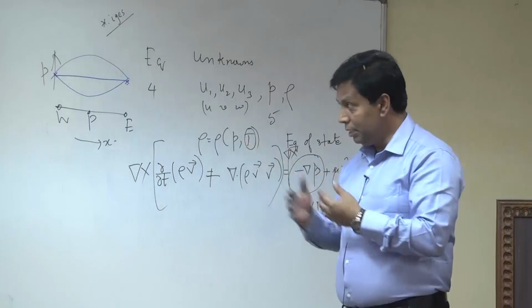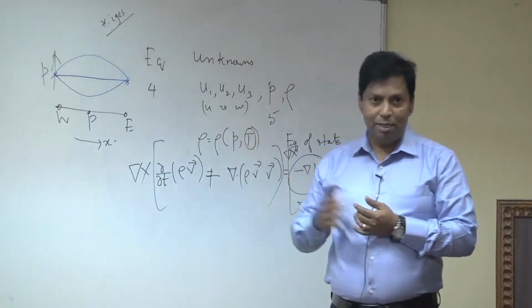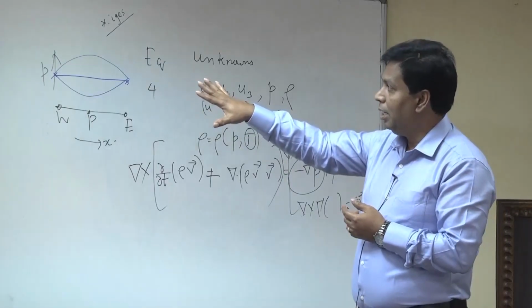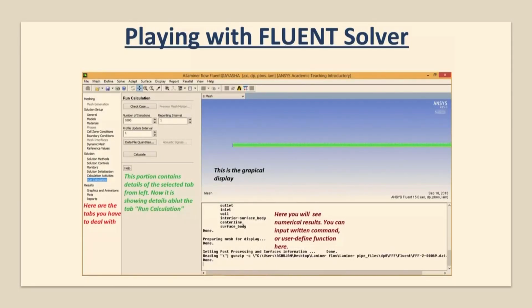Okay, so this is Fluent. When you read a mesh file, it looks like this. So the geometry, they show the mesh here. Okay, and they will give all the information here, especially all the mesh information you can see from here. So you have to check very carefully that the volume of the mesh is not negative. Sometimes if you have some error, it can give you some negative. So we have to check it.